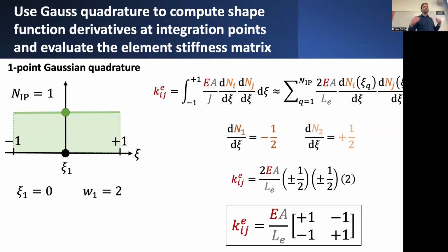So if I choose this one-point Gaussian formula to integrate this expression, choosing my integration point positions to be placed right at c equals 0, and the integration weight being proportional to the width of this whole interval from -1 to +1, what I come up with is this final expression. Evaluating this integral just through discrete evaluations of the integrand at this particular quadrature point location, c equals 0, and weighted by the integration weight 2, I come up with this expression, which is really just a bunch of different constant values of variable sign.